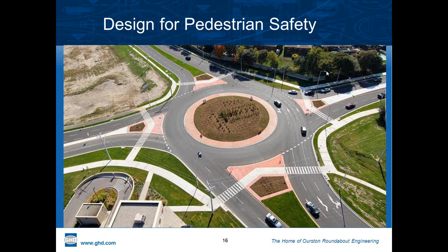And positive contrast is where the light is actually in front of the pedestrian crossing, so as the vehicle approaches, the pedestrian is vertically illuminated, and they're much more visible to the driver approaching. Now, if the light was behind the pedestrian, it would be negative contrast, and all you would see is a dark silhouette, and the light would be flooding in front of them. So we're very deliberate about placement of light poles relative to crosswalks.